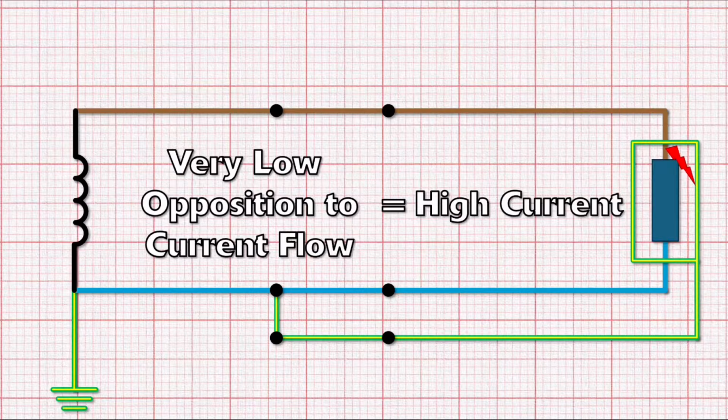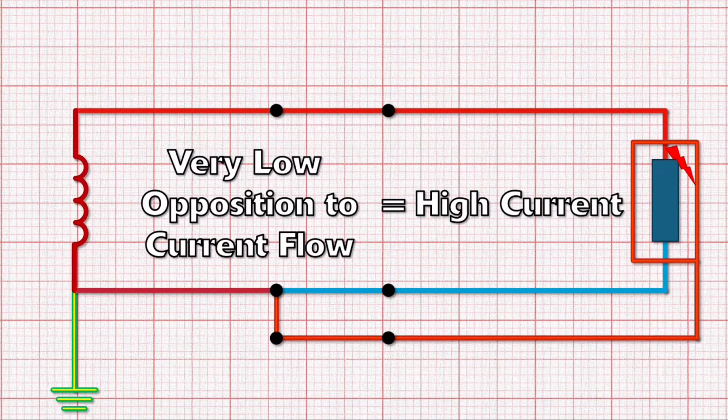One of the problems that this can cause is that large currents lead to lots of heat, and if the CPC is too small, it can't dissipate that heat safely, so it could get too hot and start a fire, or in extreme circumstances, melt the copper wire that the CPC is made from, leaving a very dangerous situation for anyone who touches the now live and accessible part. That's what we mean by thermal constraints, making sure the CPC is big enough to handle the fault current that will pass through it without causing further problems.